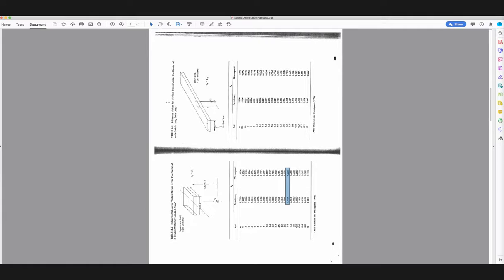What we have here is the vertical stress change under the center of a long, infinitely long strip foundation. So again, you could arrive at this table by just utilizing the graphs that were on the past 2 pages. But it's been done for you here, and it's, in a sense, quite simple access for those points of interest.